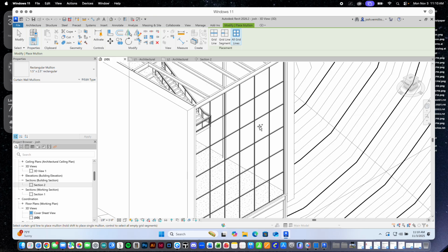Now, the north side's nice because the next time we meet, maybe Wednesday or maybe the next time, like Monday, the week from today, we'll bring our stuff from Revit into Forma, and then we'll start to do the solar analysis. What you'll notice is that the north side is not a big deal. We're going to have shade, not a lot of direct sunlight at all. On the south side, we'll have a lot, and so we'll have to start thinking about strategy for how to shade that south glass, which we can do really quite easily.